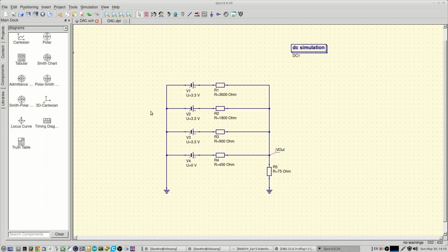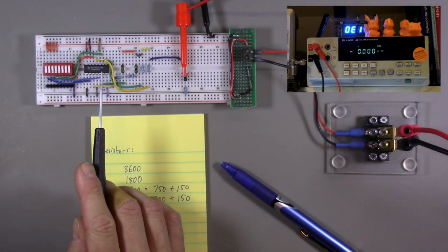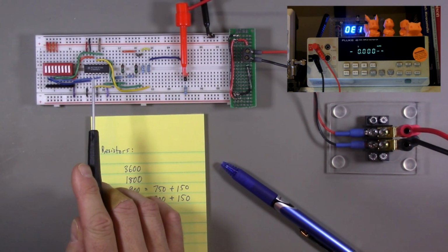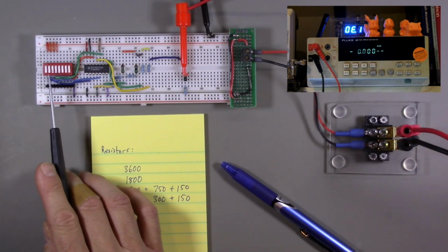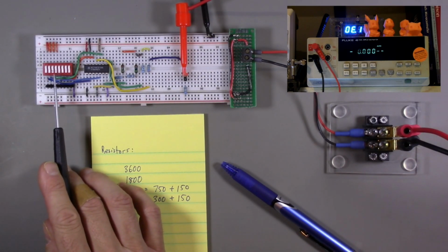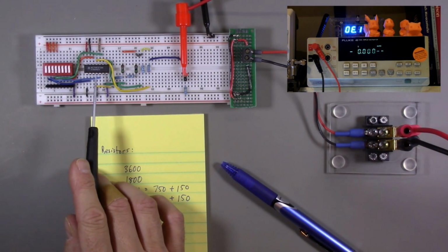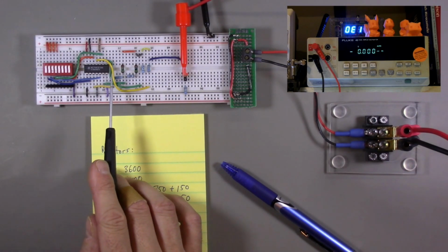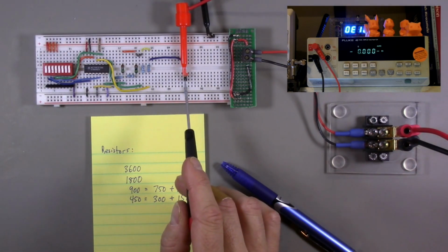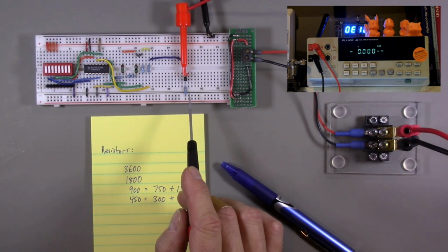So let's actually test this on the breadboard. All right, so here is our test setup. We have this 74HC125 quad buffer chip, and its inputs are driven by 4 switches in this 8-position dip switch. And essentially by turning these dip switches on and off, I can send zeros or ones to the inputs of this buffer chip, which in turn will produce digital voltages that feed into our binary weighted resistor DAC that produces then an output voltage at this point terminated by the 75 ohm resistor.